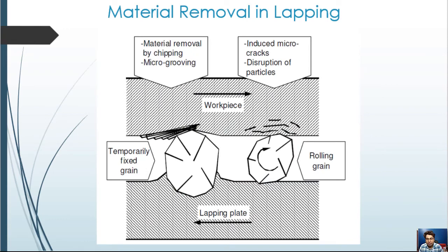Now, material removal in lapping. Lapping distinguishes itself from other machining methods in some characteristics. Most workpieces can be processed without being clamped or fixed in this process. Allowances of about 0.2 to 0.5 millimeter are economically machinable. Precision and ultra precision machining can be executed in one operational step. Changeover times are very short. Components of less than 1 millimeter or even 0.1 millimeter thickness can be machined. The highest surface and roughness requirements can be met using this process.